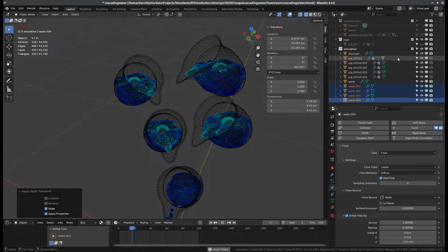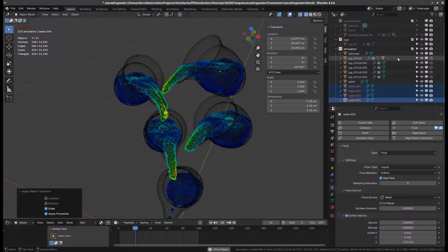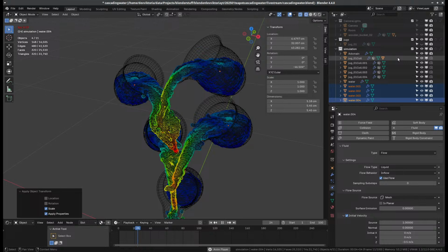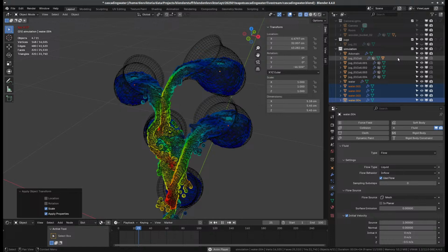I think probably I'm going to show you how I'm going to set up the materials, nothing too complicated, because it ended up pouring water into a bucket, so a simple glass shader on the domain with the IOR 1.333 will be fine. And yeah, it seems working, sort of.